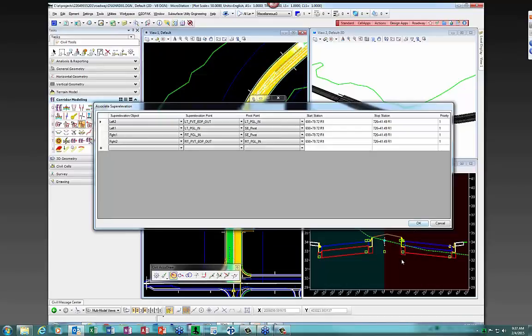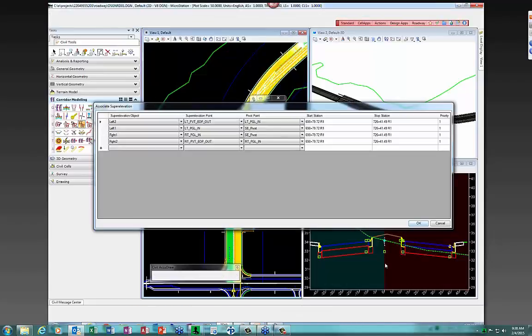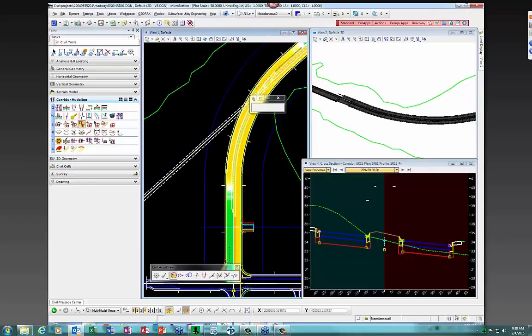And what it's going to do is recalculate the corridor and apply the superelevation lanes and transitions to the actual corridor shapes. So you can see it swirling down here. It's just reprocessing. It's applying the controls to it. It may not update the cross-section right away. Sometimes it stops swirling and then it'll come back and swirl again. But if you just keep an eye out for the little home button down here in the MicroStation dialog, this one right here, that's when you know it's finally finished.